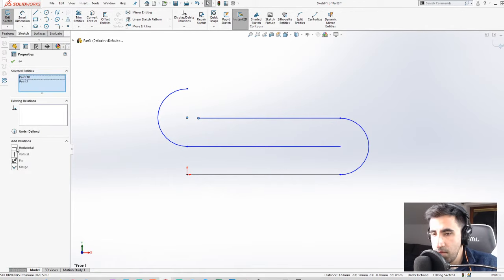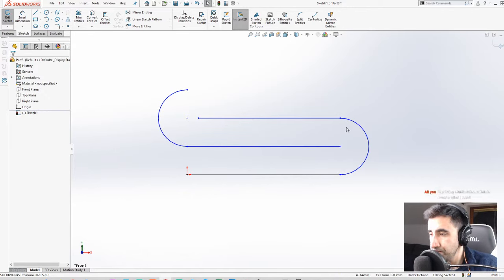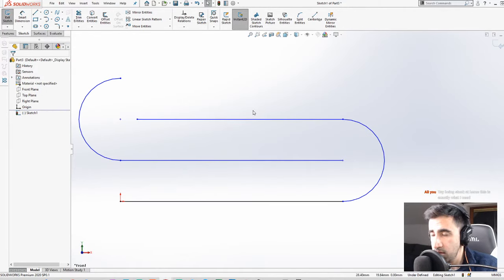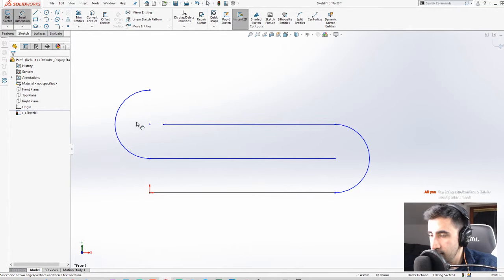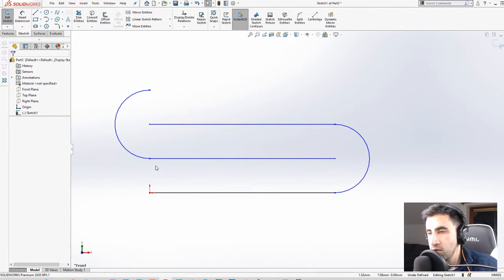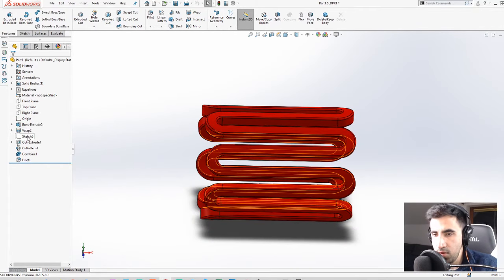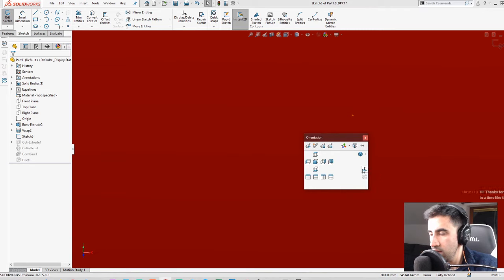So this is my base sketch. At the moment, I'm preparing the drawing in a way that could make sense. And let's just continue this over here. We need to have a base sketch that repeats itself over the circumference of a circle, and the number of the repetitions plus the distance of the repetition should come to the total value equal to the circumference of your circle. If I go back and open the base sketch and show you, I can talk.